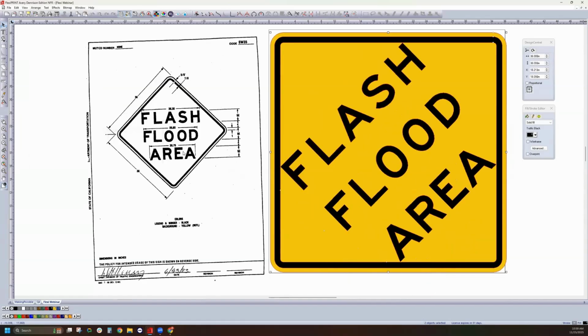And now we're noticing the issue that the original font set, or it could just be a simple typo in this original drawing, but our lettering is teetering right on the edge of our border. That's not the best for legibility. If you dig into the MUTCD, there's some information about things touching borders. We don't really want that.